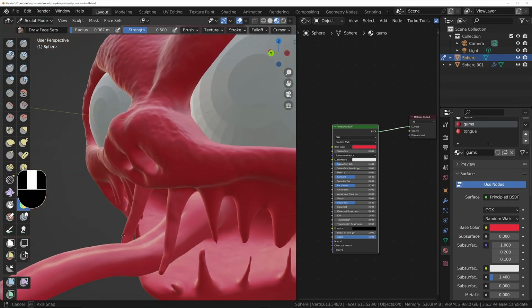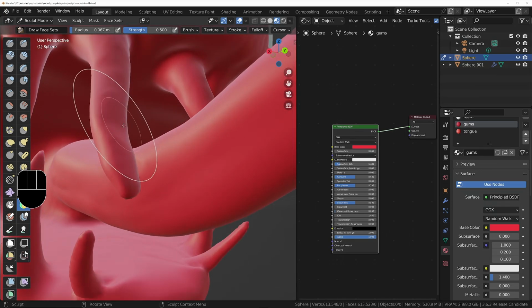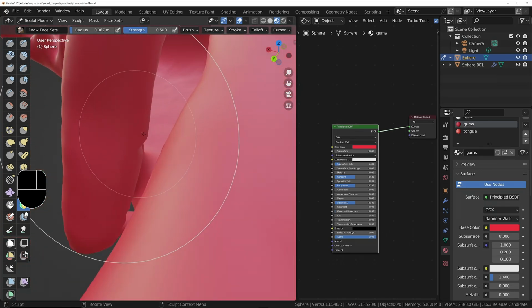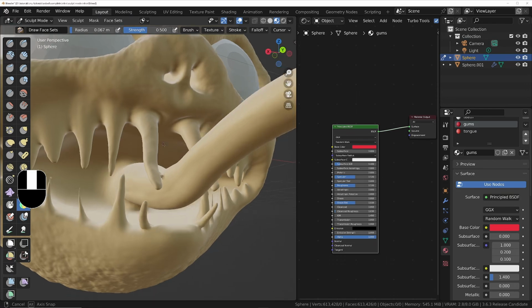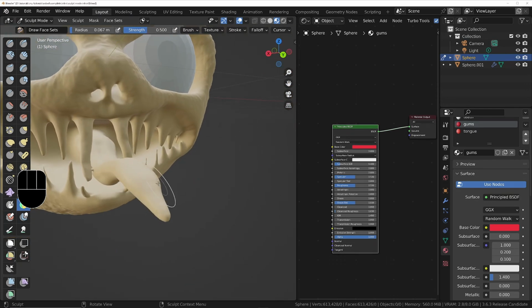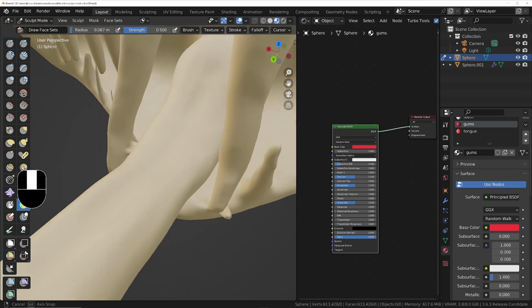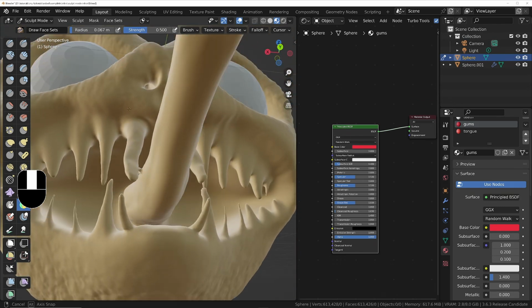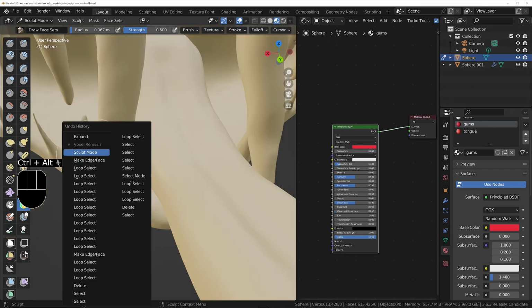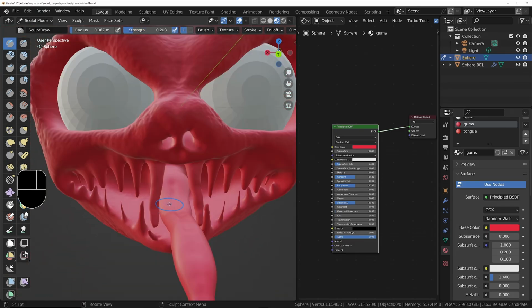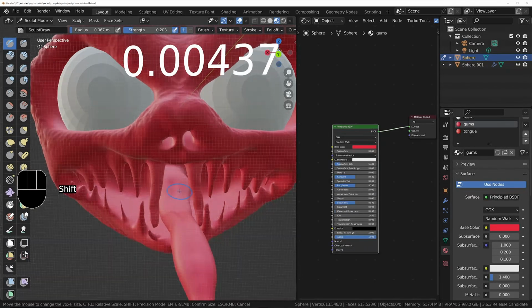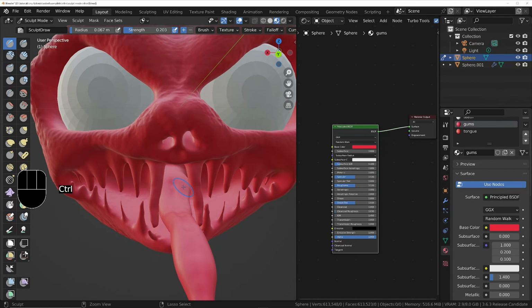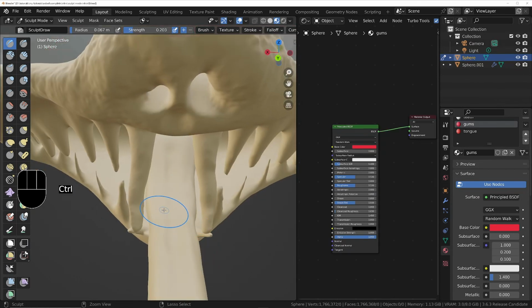And I'm going to remesh to get rid of the bad geometry, which we're going to have here, where we made that selection. So I'm just going to do Control R to remesh. That's remeshed. But unfortunately, because the remesh didn't have a low enough resolution, each of those little squares was actually larger than the gap between the tongue and the tooth. So it's reconnected it again. So I'm going to actually undo the remesh until we're back here. And then I'll press R to change the remesh size, so we've got smaller squares, so that that gap doesn't get automatically joined when I do the remesh. Press Ctrl R to remesh, and now we're no longer getting that problem.